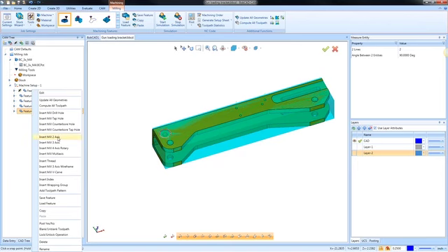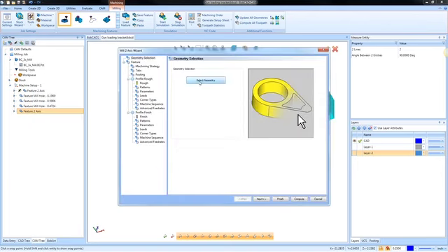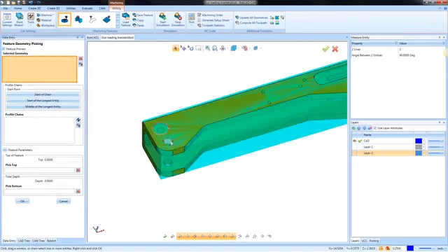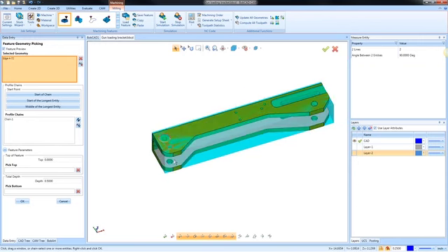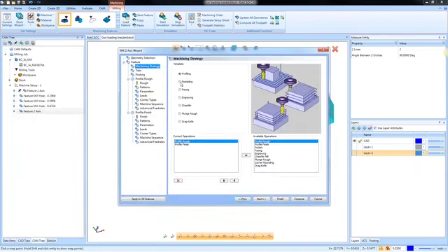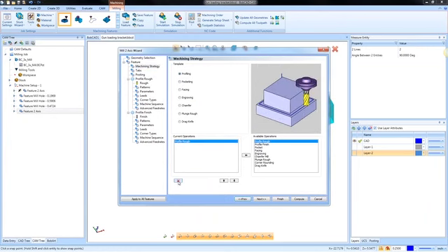We're going to go to Insert Mill to Axis. We're going to go to Select Geometry. I'm going to select this hole here and this hole there. I'm just picking the top of it. I'll pick the bottom, so I'll say that's how deep I want it to go. I'm going to add a punch through of 100 thou. So that's the geometry that I want to run, and then how deep I want it to go. In this case, I'm going to do a profile rough routine.